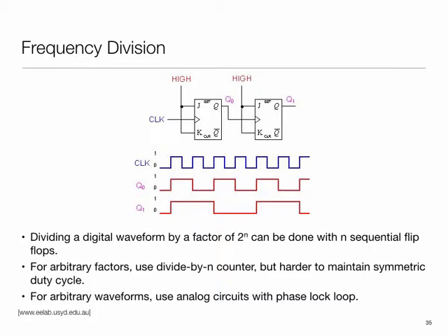The other thing you would notice is that a lot of standards have very weird requirements, like USB operates at 480 point some megahertz and things like that. They're very peculiar requirements that come up. Some of them basically arise from the commonly available clocks. Some of them also have other sources. So how do we get to those clocks starting from what I actually have? So again, division by 2 to the power n is very easy.